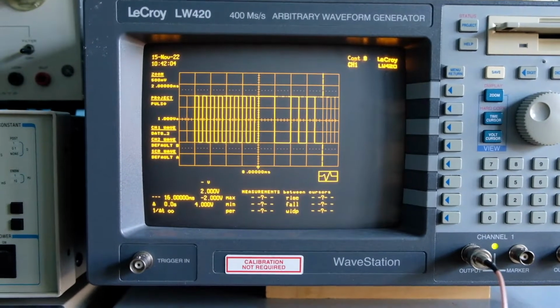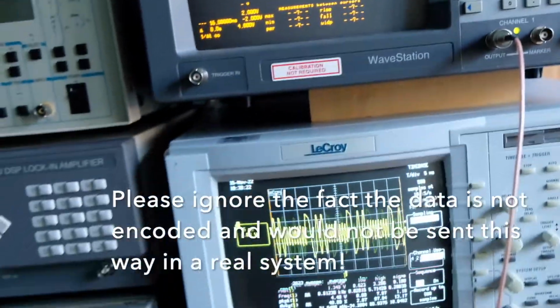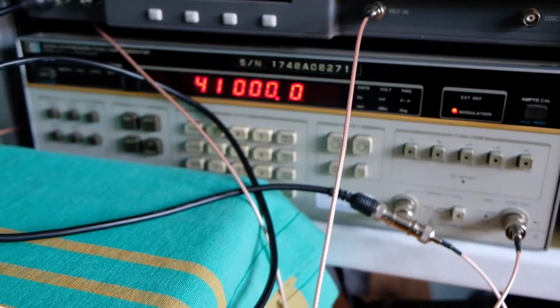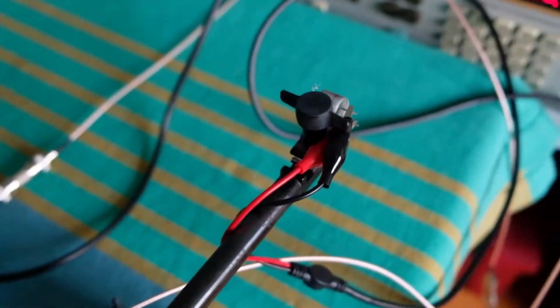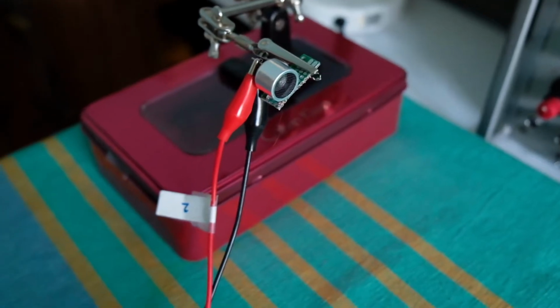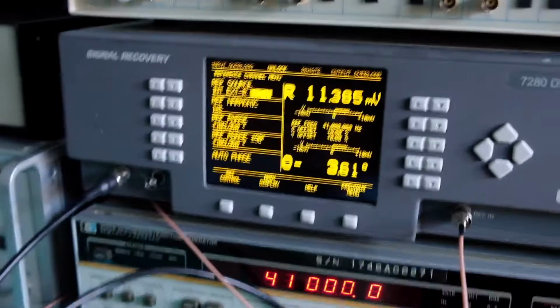What I have here is somewhat random data. So that data is now going into the modulation input of my HP3325A, which is producing a 141 kilohertz ultrasonic tone, which is then modulated by this lower frequency data. That goes into this transmitter of the ultrasonic driver over here, and that's placed about a meter or so away, and it's being received by this other receive sensor, the output of which goes to the lock-in.